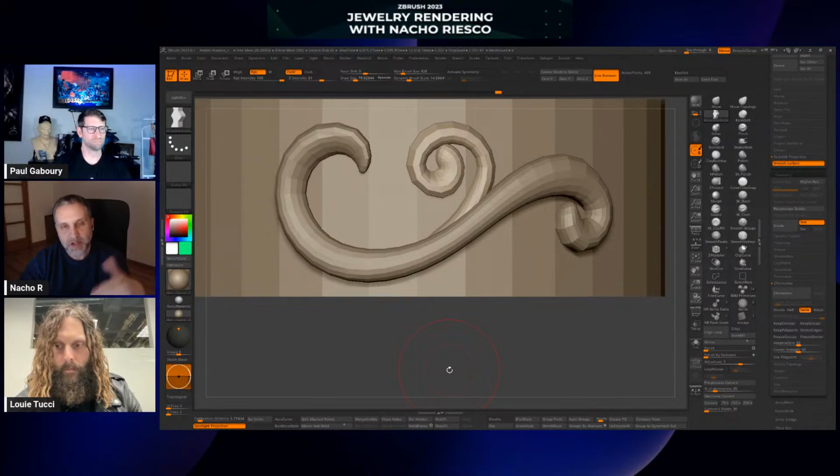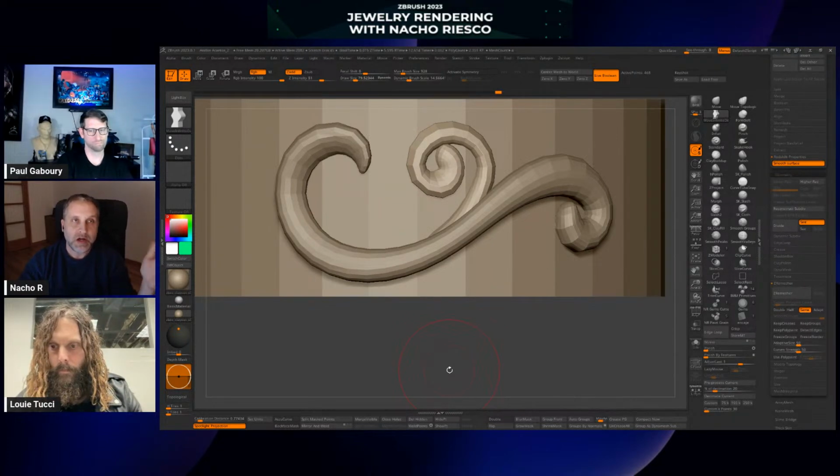So you should be worried about the weight during the whole process when you're creating a jewelry piece, depending on the kind of metal. Even more so if you are creating a gold piece. That's the reason why I use Mesh Mixer, because we have more control with the offset of the external and the internal wall. For example, a client yesterday requested me to sculpt a figure with 0.6 millimeter wall thickness. So we're going to save a lot of metal, using a more precise approach.